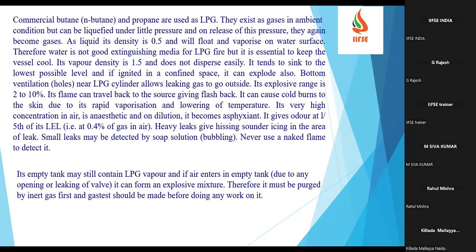The liquid density is 0.5, so it will float on and also vaporize on water surfaces. Therefore, water is not a good extinguishing media for LPG fire, but it is essential to keep the vessel cool. Its vapor density is 1.5 and it does not disperse easily. It tends to sink to the lowest possible levels because of vapor density. As I mentioned, vapor density, like chlorine, it also has a tendency to sink.